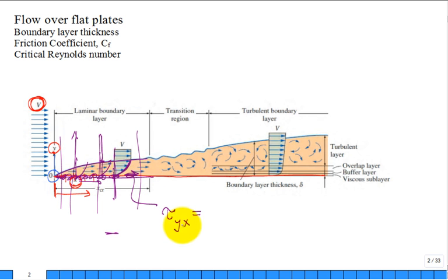So how would we calculate this? Well, the viscosity, and then we would have the rate of change of u with respect to y at y equal to 0. What law is this? Law of viscosity. And so if you know the velocity profile u as a function of y, then you can get the derivative of it, du/dy, and evaluate that derivative at the surface y equal to 0. Then I have the ability to calculate the surface shear stress and calculate then the total viscous drag on that plate by integrating.